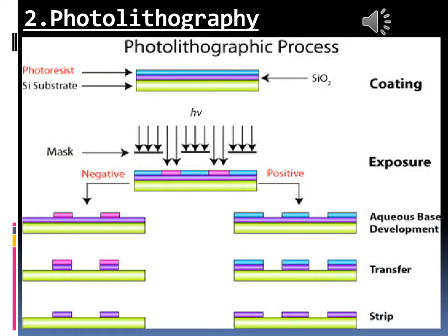What is lithography? Lithography is the transfer of geometric shapes on a mask to a smooth surface. In modern semiconductor manufacturing, photolithography uses optical radiation to image the mask on a silicon wafer using photoresist layers. Other methods are electron beam, scanning probe, X-ray and EUV lithography.